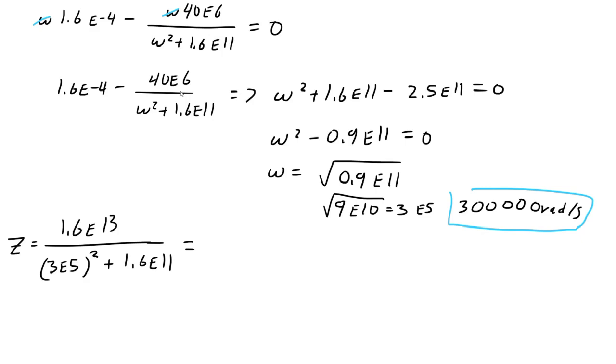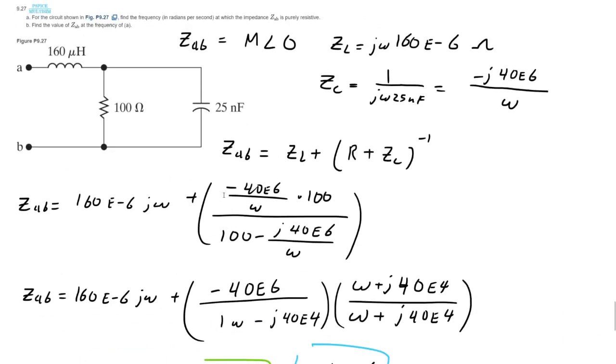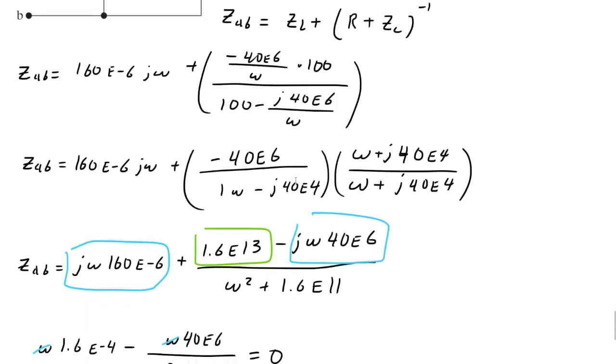Okay, I get 64 ohms as the impedance at that frequency. So, yeah. And the phase angle is going to be 0, because once I said it was purely resistive, we have no phase angle because we made sure that the frequency was where it canceled out.